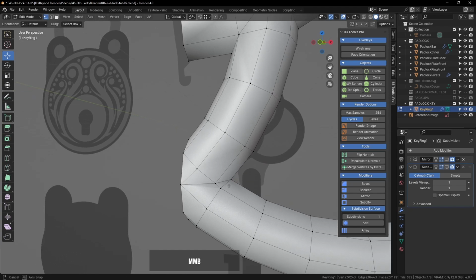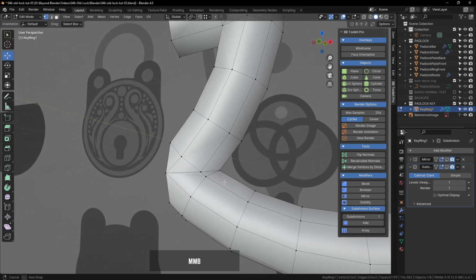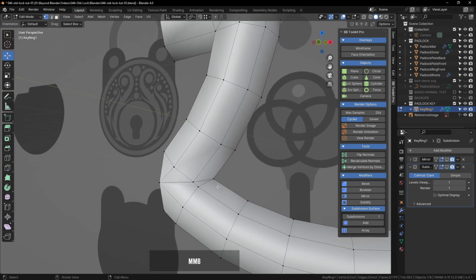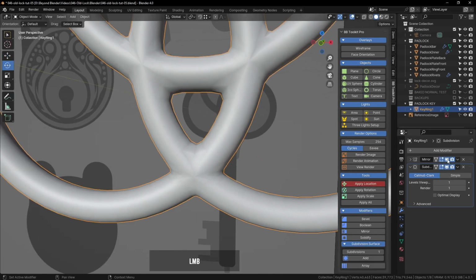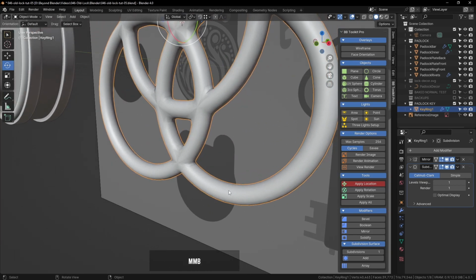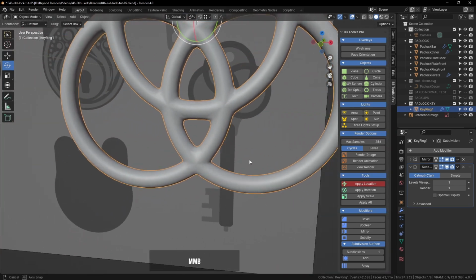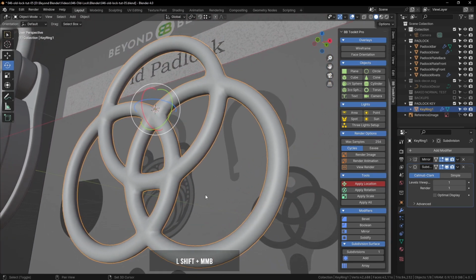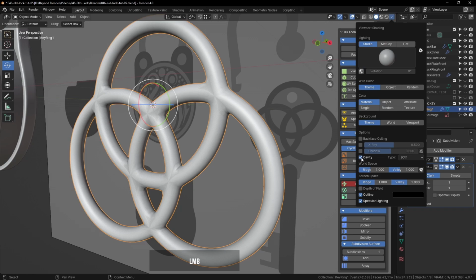As you can see, I'm just still going through the same process, step by step, cleaning up the geometry and eliminating any potential problem areas. You can see that I've used the knife tool to add a better loop there and toggled the subdivision modifier to see how that behaves. You can turn cavity off, which I like to have, as it really helps to visualize the 3D in the viewport. So I turn that back on there. You can see how much nicer that is to see how things are working.